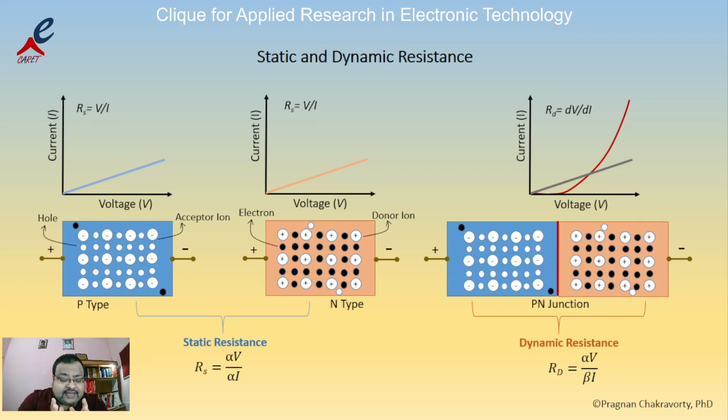That means there is a higher concentration at left and lower concentration at right, and this creates a diffusion current on top of the conduction current which already exists. This diffusion current actually changes the charge density at a given location with the change in the voltage, which is why we also see a non-linear current and a dynamic resistance.